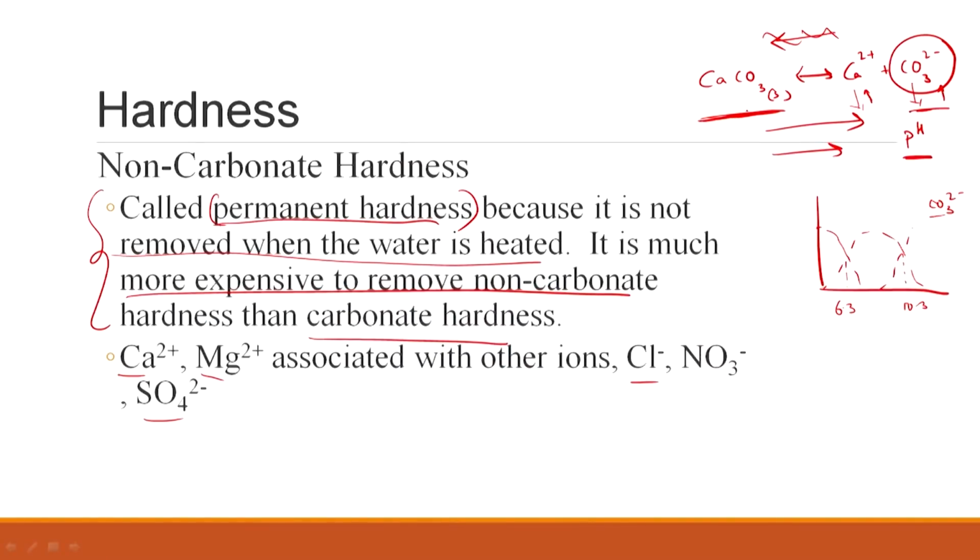But with respect to calcium and magnesium associated with sulfates, say CaSO4, I am not sure if it will precipitate out, but let us assume that. Now, we have that in equilibrium with Ca2 plus and SO4 2 minus. And if you look at the pK of HSO4 minus, you know that it is either negative or 0. So, you need to bring down the pH to unacceptably low, practically infeasible levels to be able to reverse this precipitation.